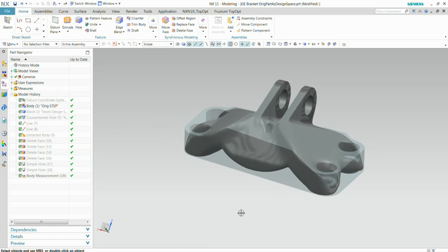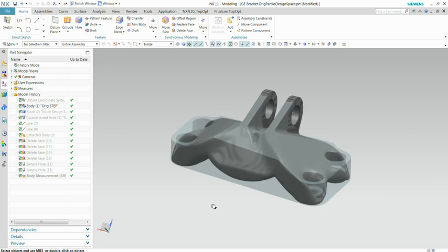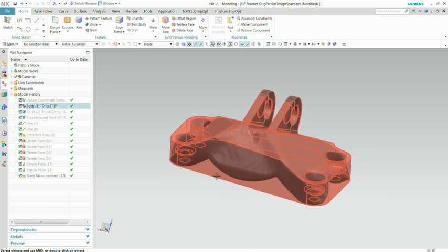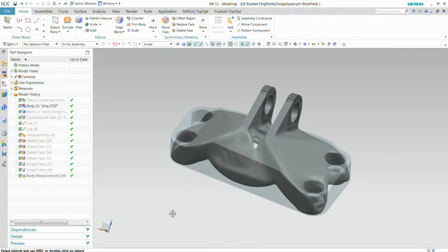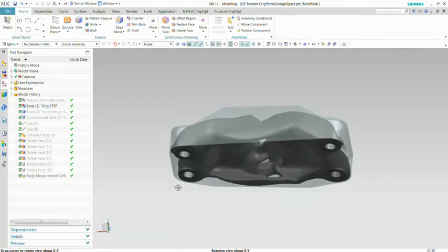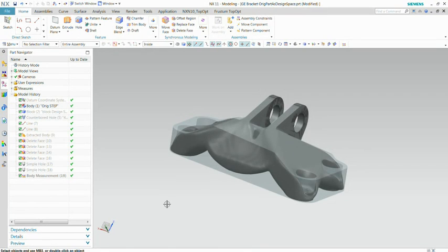Another example of an optimization is, for example, this bracket. It was used for a contest on topology a few years ago, but here you see, for example, the design shape of a volume where we allow to have material, and you see here inside the optimized shape of, for example, this bracket. So it's a method that gives you, in a very fast way, already some shapes that can inspire you for your final product. And because of the precision of the results, maybe it's already good enough for direct production purposes.